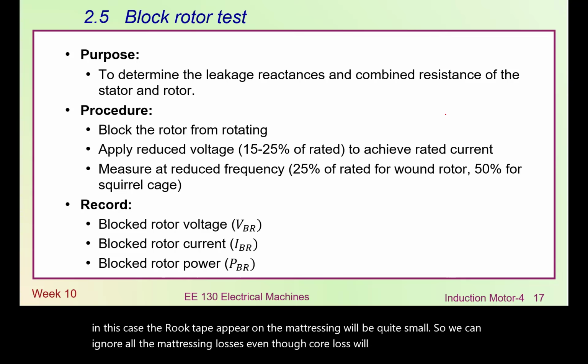So that means here we can ignore the core losses and magnetizing. We assume all the losses go to the motor winding and also X1 and X2. Now we can use this method to estimate the leakage component. So the component here becomes like that. This magnetizing branch can just be ignored for the moment because the voltage here will be really low.